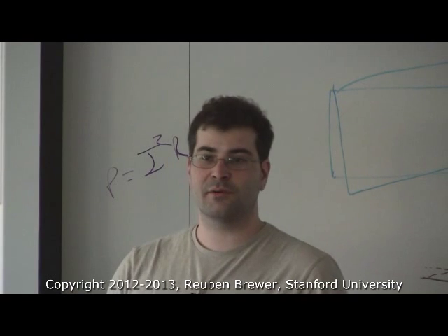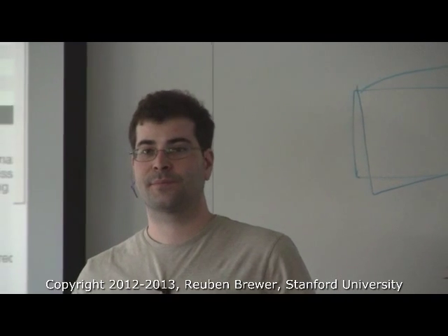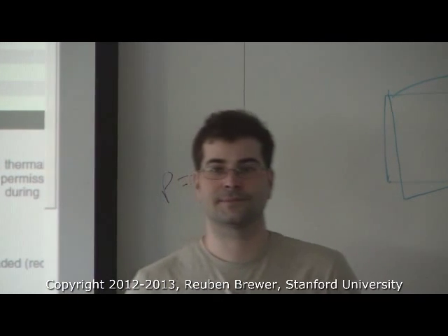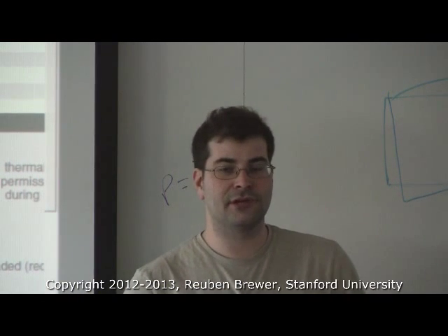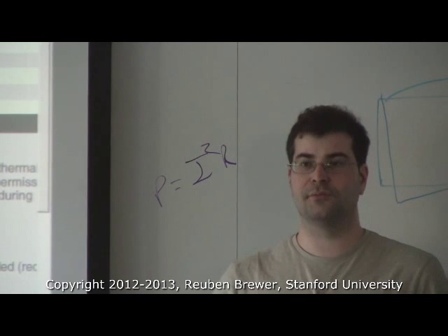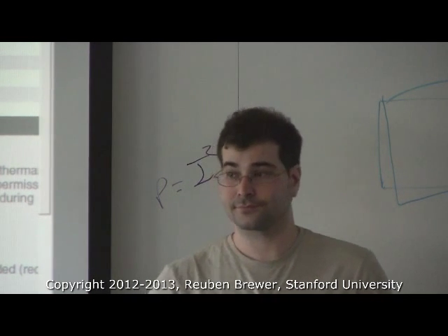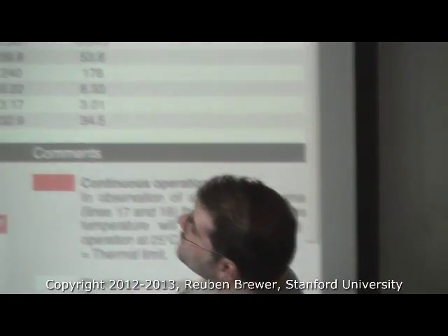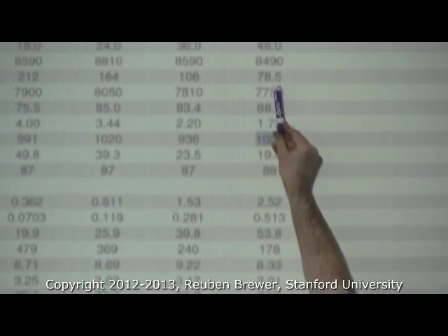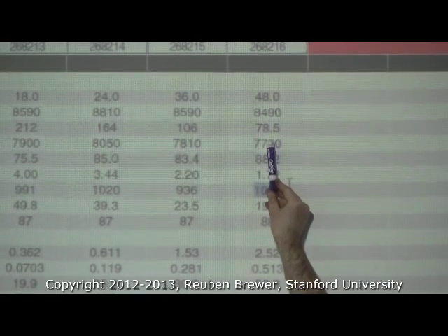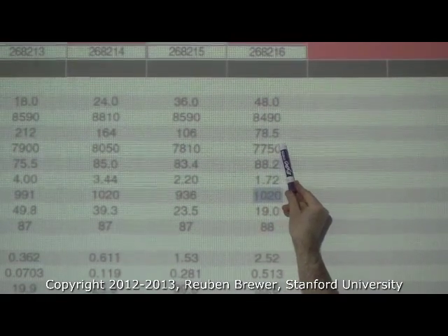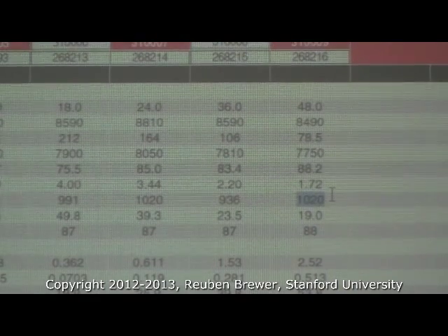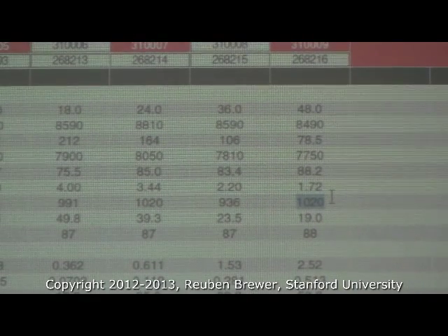So has everyone felt how shitty those motors are? Those were driven at stall torque for too long. If you drive at stall torque for too long, your motors will likely feel like that. Well, this is kind of crappy, right? Because the no load current is through 78.5 milliamps, and stall torque is 1.02 newton meters, roughly a factor of 10 or 11 above the continuous torque.